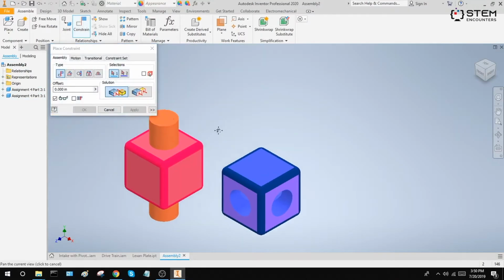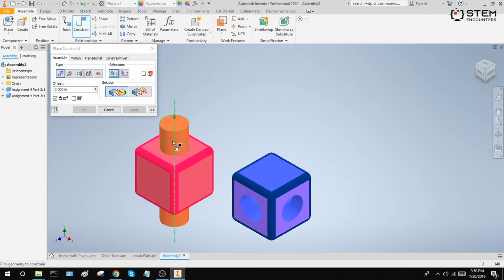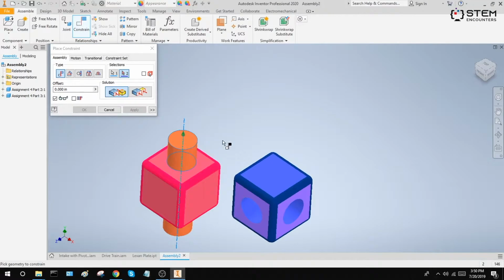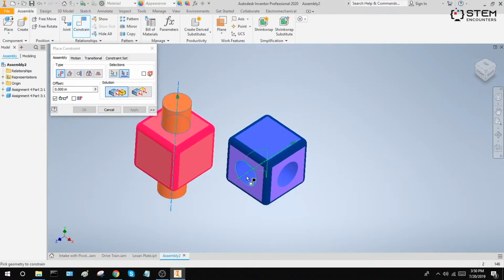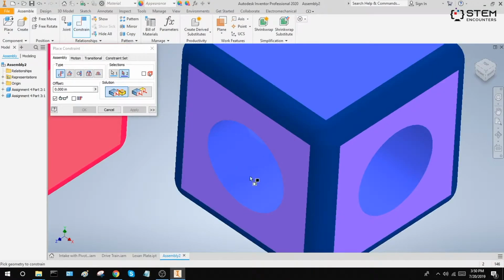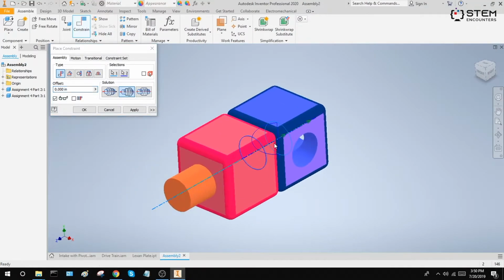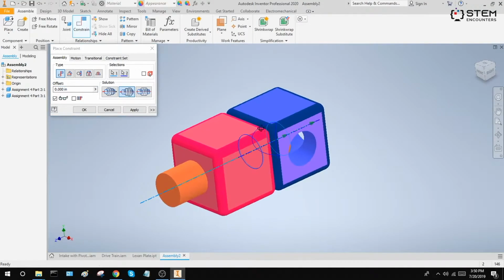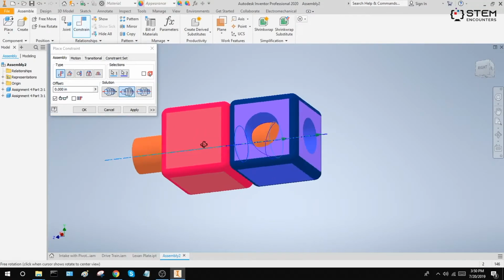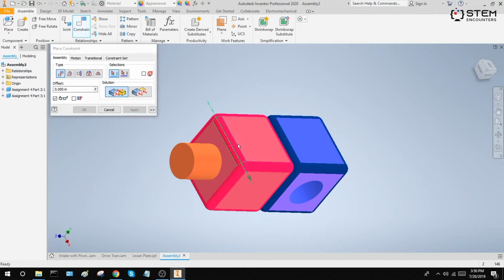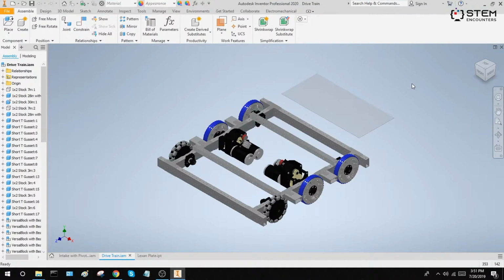And that's why when we constrain an object into a hole, when we select the central axis, we're creating a line. And when we select the central axis of the hole, we're also creating a line. And by mating the two, we're having those lines coincide, which is why the alignment occurs where the object fits into the hole. Thinking about a mate in this more geometric sense helps you visualize a lot more types of constraints that you can do.